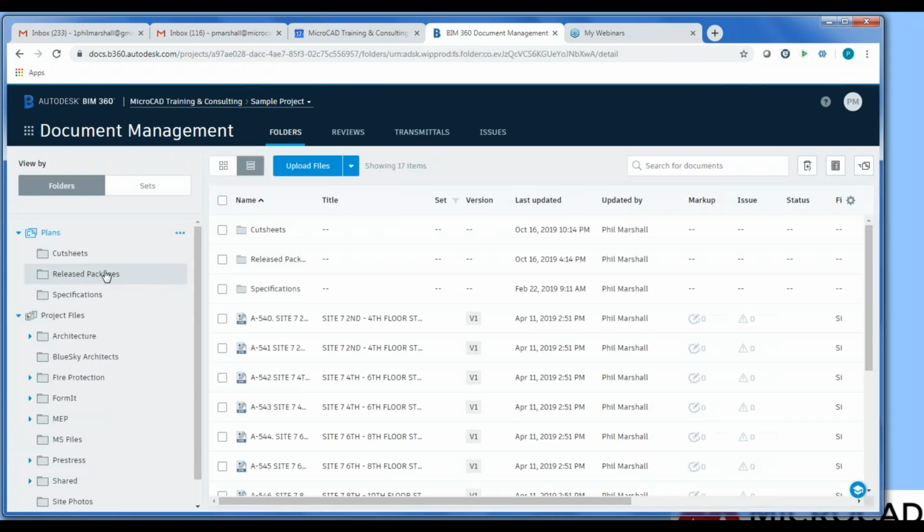You see that within this project there is a folder structure to organize data. The folder project files holds the BIM models and associated files, while the plans folder holds the published construction documentation. You can add any subfolders you like in this structure. The folders do have some intelligence. For example, BIM 360 Design uses the project file folders for Revit work shared projects. When you form teams for the projects, you can set the user's default working location so their work is automatically saved in that location.